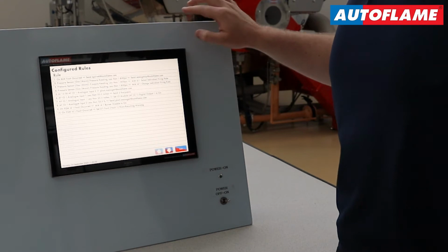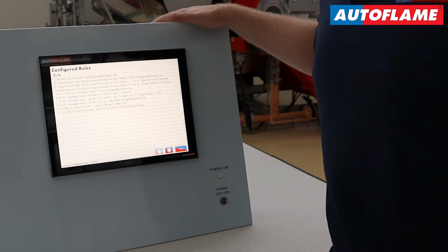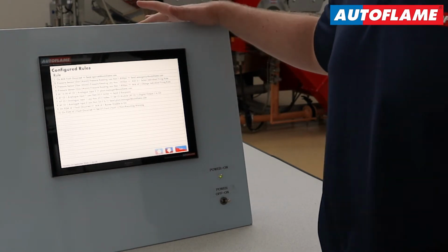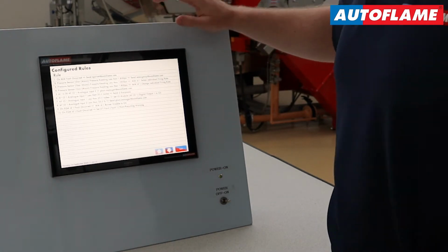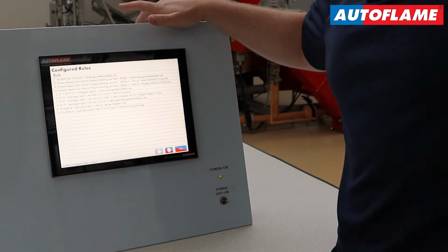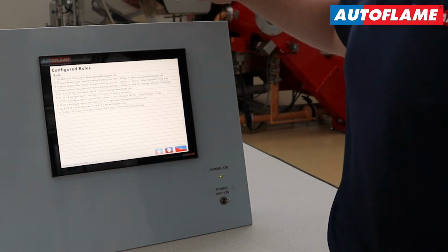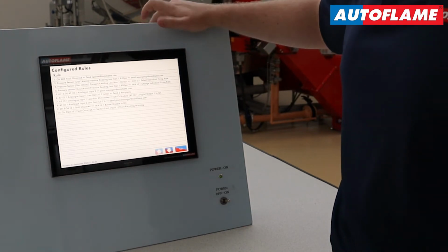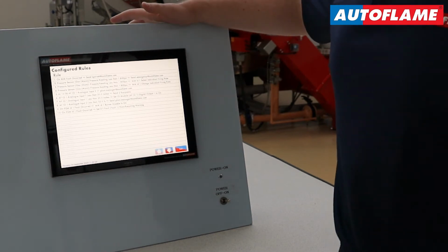Okay, so for my gas pressure sensor, which is hooked up in my main gas line, I have 3 different rules set up. Different outputs, but the same input. So I've set up a threshold. When my reading from my main gas line pressure sensor drops below 1.8 psi, I'm going to do 3 different things, 3 outputs. First one is to send an email to